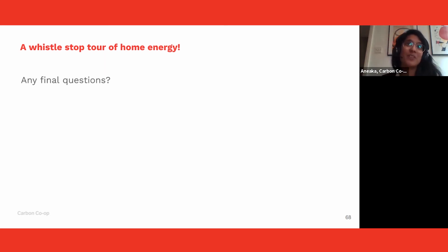So the reason I'm going into all of that is it's more than thinking about whether I should put an air vent in this room. It's about thinking about the whole house, how air flows through it, and how I can control it so I don't lose too much heat, but still have enough air movement to keep the air inside your home fresh and get rid of pollutants as well as extra moisture.